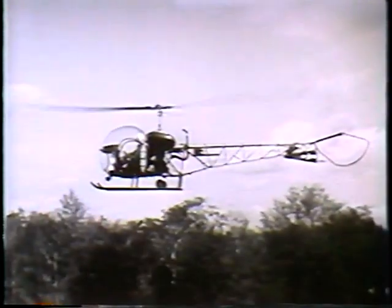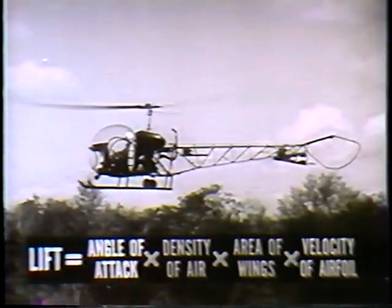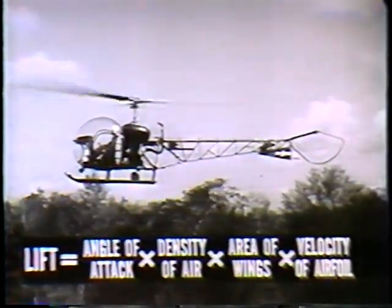However, man wasn't born with built-in flight instincts, nor did his mother teach him aerodynamics. Since that part of your education was neglected, we'll try to supply it in part. First of all, it is necessary to understand the factors which give you lift. In general terms, lift equals angle of attack times density of the air times area of the wings times velocity of the airfoil through the relative wind.